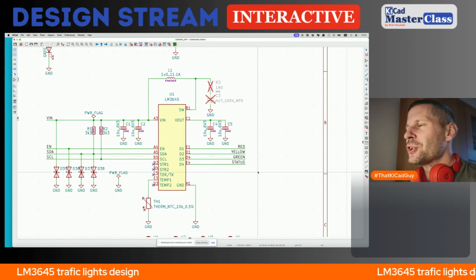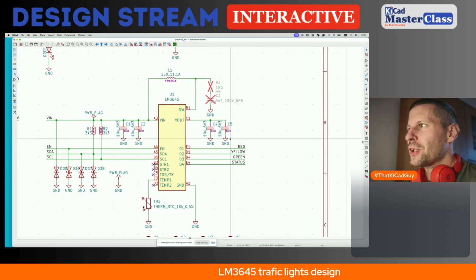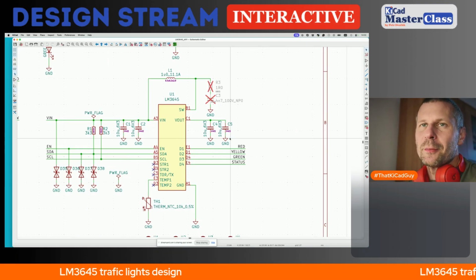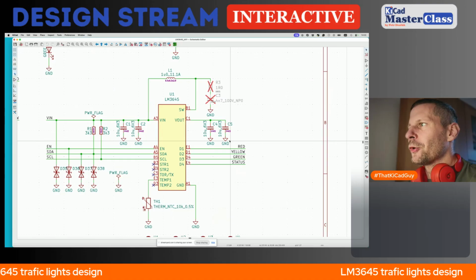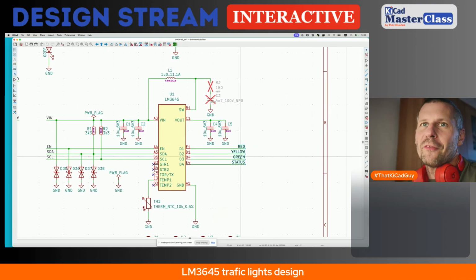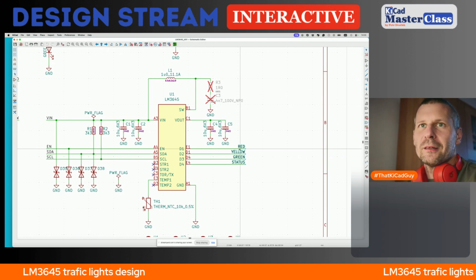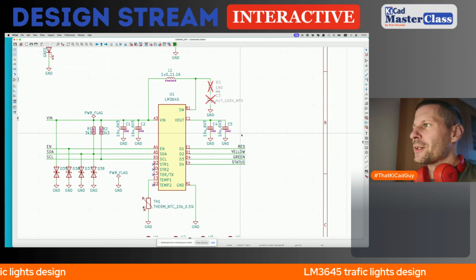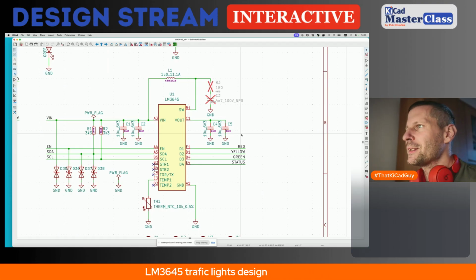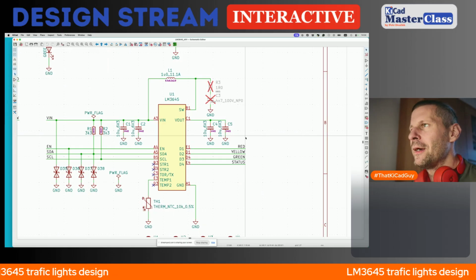And as the datasheet says, the maximum current per channel is 500 milliamps, which is probably the limitation, not the total current. It doesn't mean that it's 1.5 amps on one channel and the rest shares the remaining 500 milliamps. This is not the case. The case is that 500 milliamps per channel is the limit.